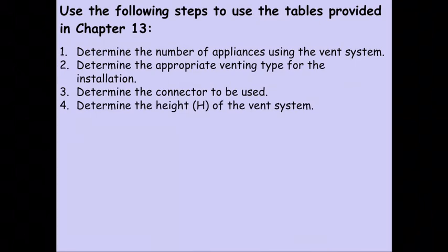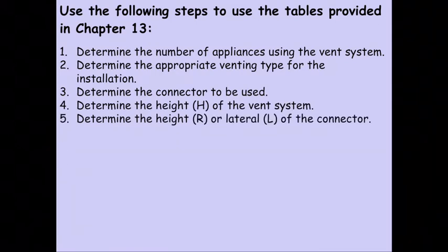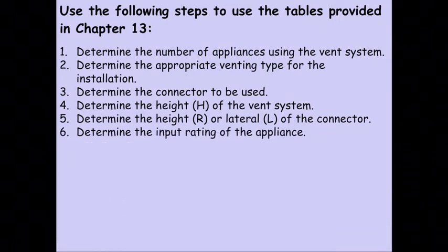Determine the height of your system. For any application, when you're going to connect up the vent system or design it and figure out what size you're supposed to use, you're going to have to estimate what your vent heights will be. You're going to have to estimate what your laterals are going to be. You're going to have to find out what's going to go into the system to make sure it's going to work. And then obviously you're going to have to figure out the input of the appliances you're dealing with.